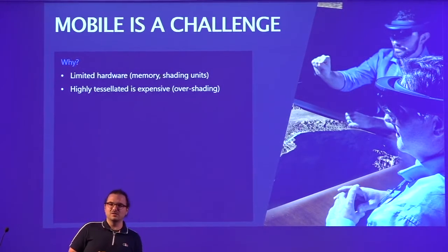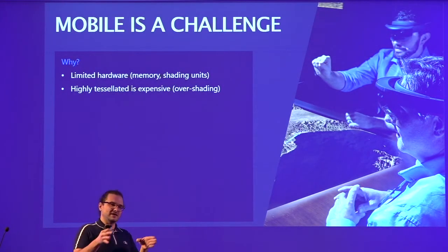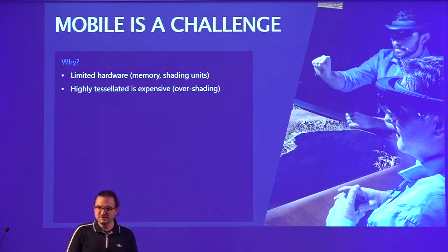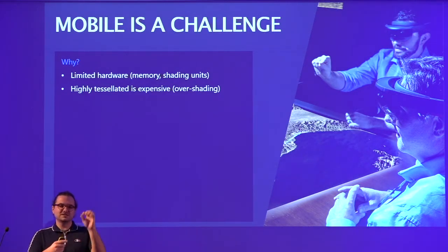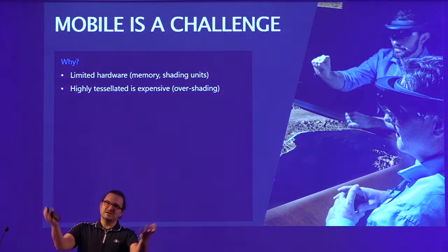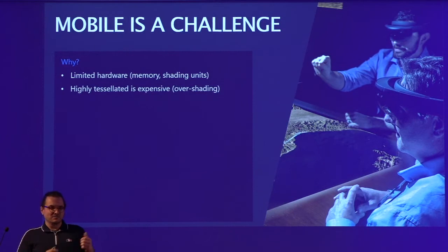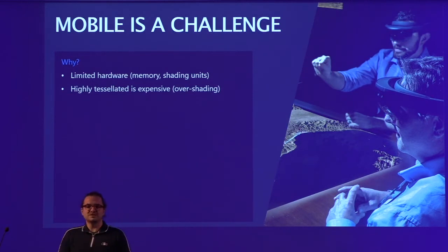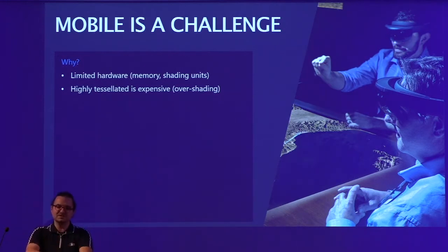When we deal with CAD models, they are represented in a different way than how modern graphics cards render 3D content. Graphics cards understand vertices, they understand points, and then connect them as triangles, and then they form a mesh, right? That's what a graphics card understands. But typically in a CAD program, in a CAD world, those models are represented in a parametric fashion. Let me give you an example, a beam, which is a cylinder, right? The cylinder is represented as a point in 3D, the length of the extrusion, and the radius or diameter. That's how a CAD program typically represents it internally. But in order to render it, you need to convert that representation into a geometry. That's the tessellation step, right?